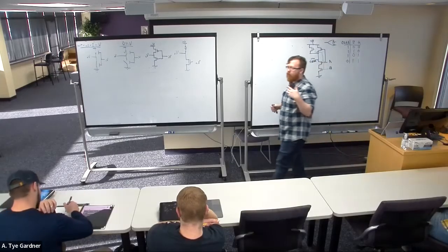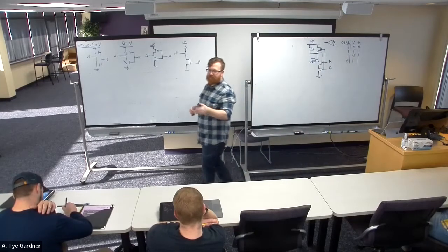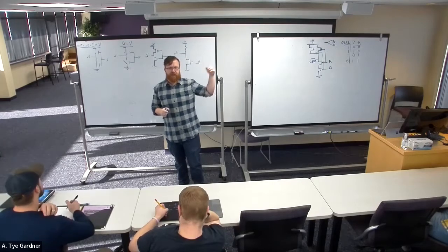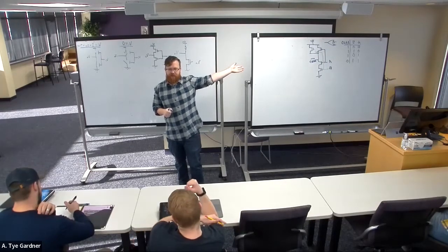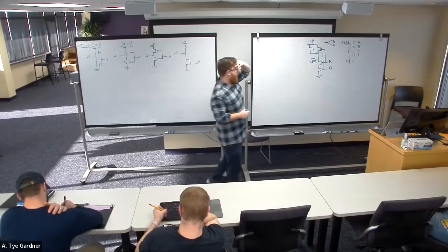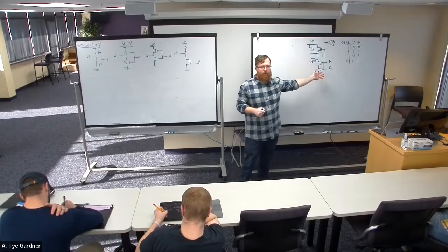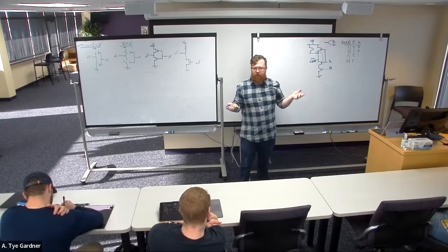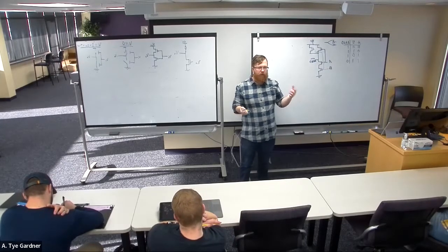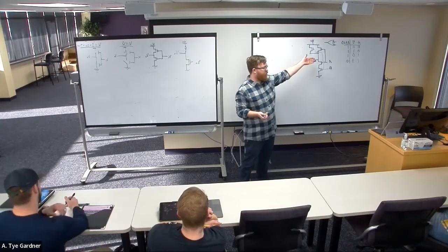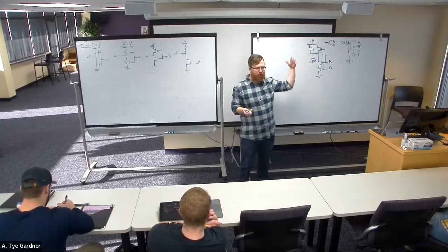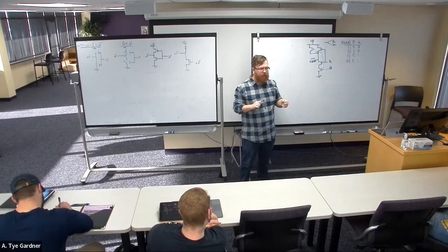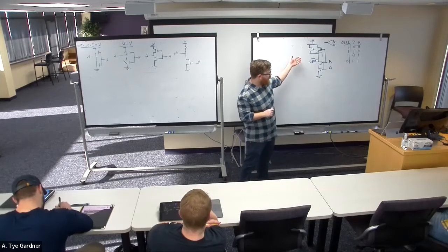I've had you start by analyzing circuits, and then you started designing circuits using the abstracted gates. Well, you get to do the same thing with these, where I might give you a picture and ask you, what does this device do? And the first step is to draw out the truth table, right? And you can redraw this four times, with the various switches closed, and see what the output is connected to.